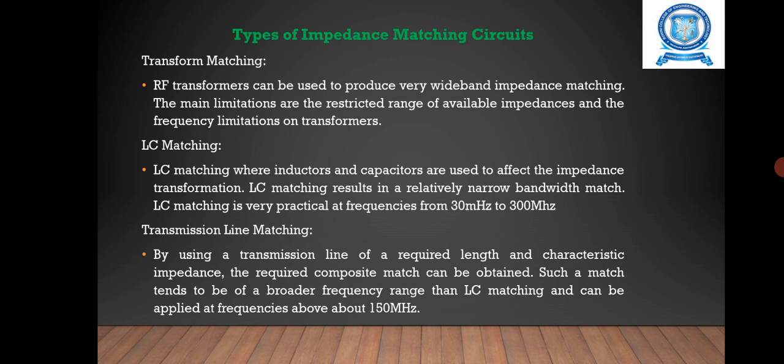Then the next one is LC matching. Here inductors and capacitors are used to affect the impedance transformation. LC matching results in a relatively narrow bandwidth match, and it is also very practical at frequencies from 30 MHz to 300 MHz.